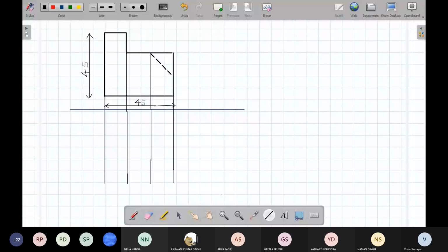Okay. So these thin lines are actually projected lines. They are not edges. Remember, edges are shown in thick. Can you differentiate between these thick lines and thin lines? Thick line is to represent the edges of the solid, and thin lines are also known as helping lines to draw. Now I am going to use thick line to draw the drawing.